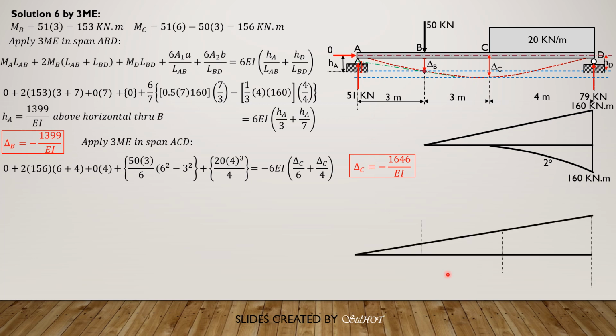So this is the moment diagram of the original whole system. So 350 over EI, then we have 160 over EI, a second degree curve here. Then this is 150, 50 times 3. This is 153, and this is 306 over EI.